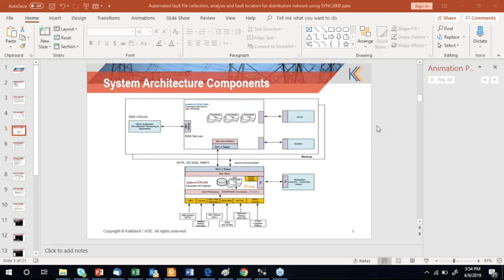This scenario we do in the PSCS tool, which is available at the center, so that whenever it receives a ComTrade file, it analyzes the digital channels and takes those events, and they can be seen in the event list. We are also working in one of the tenders to convert it into CSV and push it to the central analysis system. So the analysis system will have the ComTrade file, plus the events extracted from the ComTrade file, plus live events from the IEDs also. So the answer is yes, we extract the events from the ComTrade file and make them available in the event list, and we are working on making them available in CSV format from the ComTrade as well.